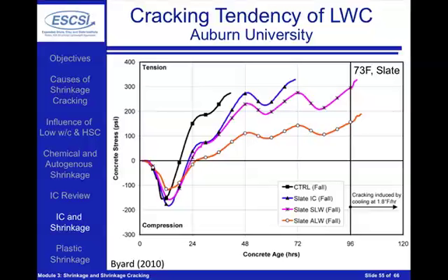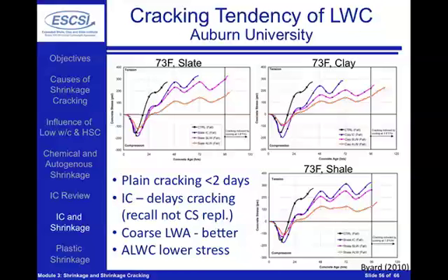If you're using an all lightweight concrete or a sand lightweight concrete, you can see the orange and the purple curves respectively that are again reducing more and more of the stress that's inside of the system. Again, it's important to note here that this internally cured concrete doesn't contain the full volume of water that would be needed to essentially replace all of the vapor-filled space caused by chemical shrinkage. And you can see here that this was done for many different types of aggregates that were made by expanding clays, shales, and slates, and in all cases the internally cured concrete delays the age of cracking.